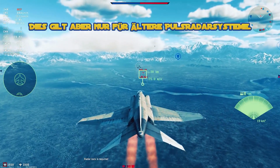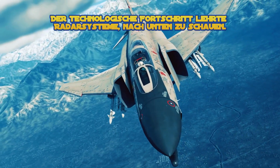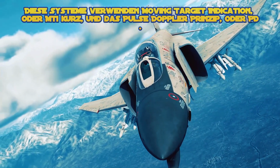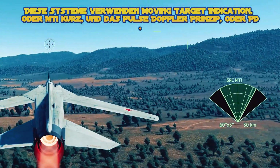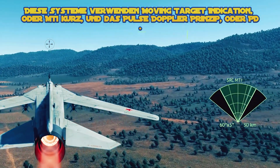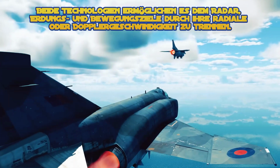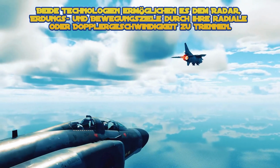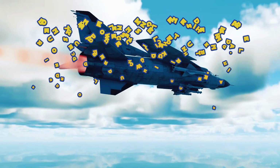But all of this is only true for older pulse radar systems. Technology progress taught radar systems to look down. These systems use moving target indication, or MTI for short, and the pulse Doppler principle, or PD. Both technologies allow the radar to separate ground clutter and moving targets by their radial, or Doppler, speed.